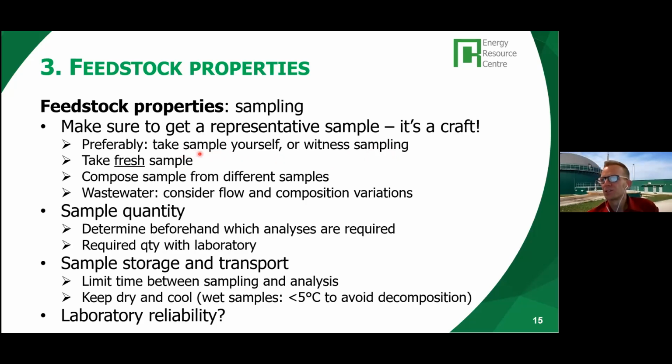Whether it's taken from the right process, whether it's a fresh sample, whether it's composed of the right flows of biomass. And it's important that you either take the sample yourself, or at least you witness the sampling. So if there's any unexpected outcome from the analysis, you may have a starting point for the explanation of this.